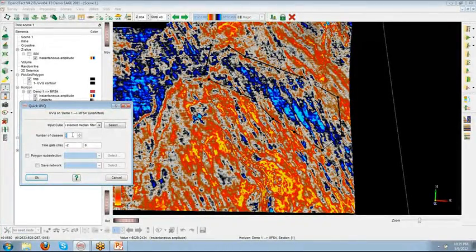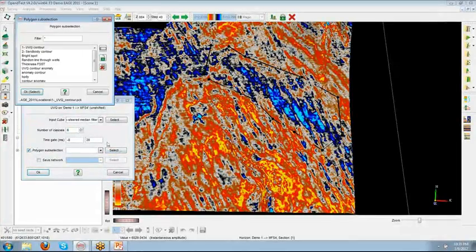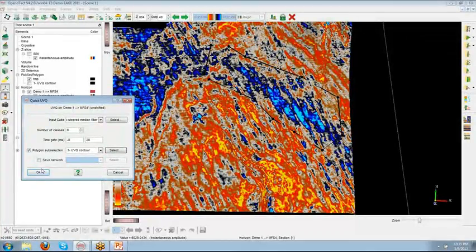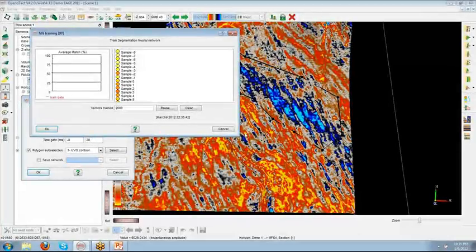It will load the seismic data in a very small waveform, here -8 to +28 milliseconds relative to this top horizon. And it will try to cluster all the existing waveforms from the seismic volume into 6 very distinct classes that are themselves the output of this training. I'll also provide the contour polygon to limit this classification to only the eastern part of the survey.